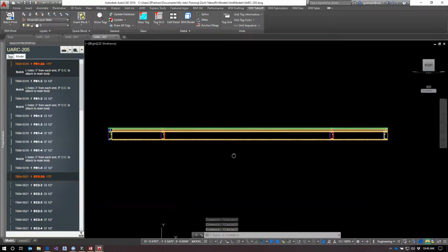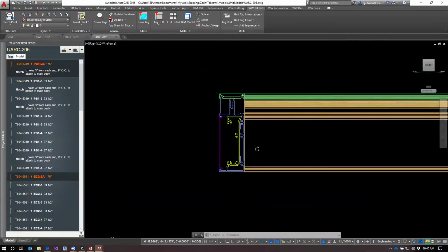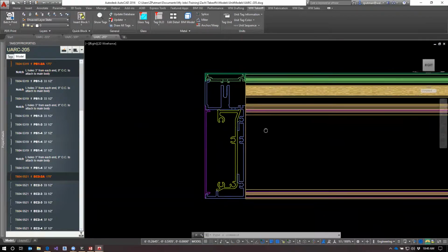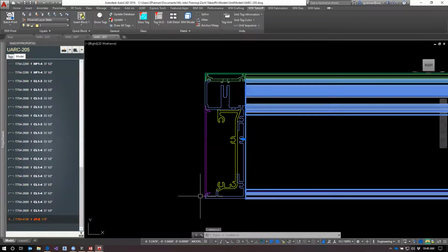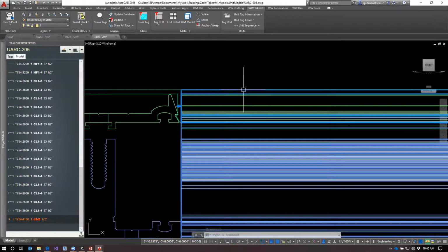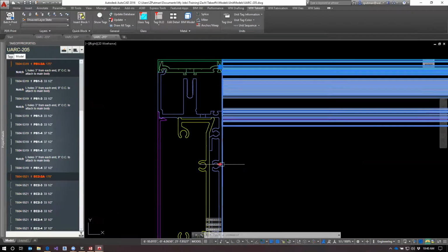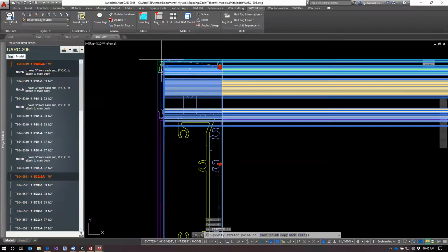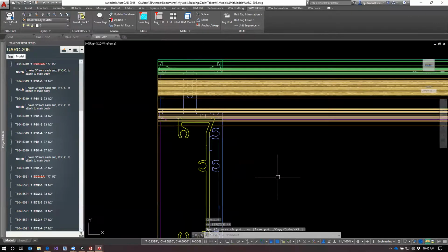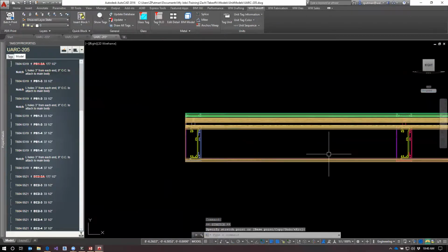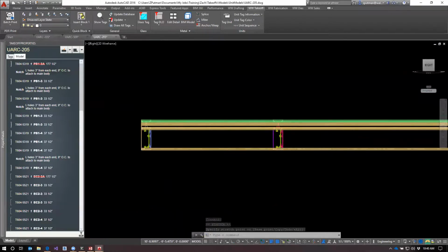Let's do the bottom. And then after that, we'll save this. So same thing at the bottom. Here's my vertical. It should be running all the way to the bottom of the sill. Same with my cover. Same with my pressure bar. So I'm going to hold down Shift, select all of these grips, then let go of Shift, click again, and drag them all to the bottom. Done, at least with that vertical.